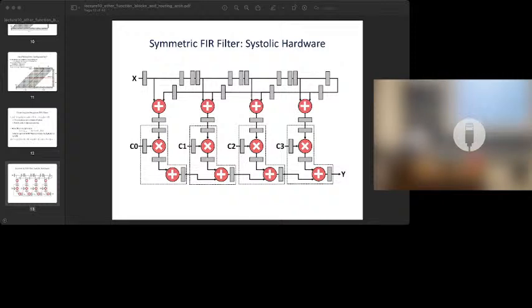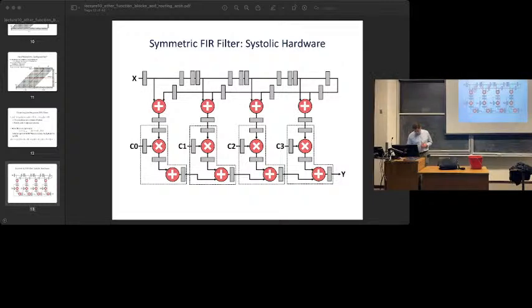To make it fast, there are registers on the output path as well. And to make the pipelining work, that's done the way we talked about in class, where you draw cut lines. You actually have to add those registers on the input as well. This is why instead of having just a straight shift register, we have some extra registers. It's to line up the latency with these extra registers that were put in the output path for speed.